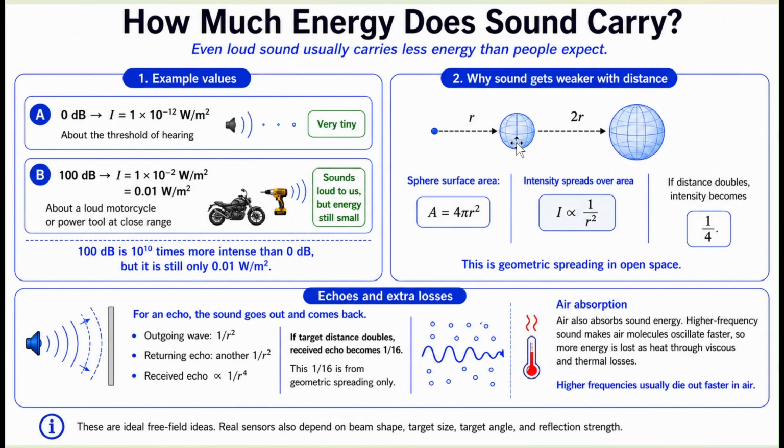So if in this small ball we had 1 unit of energy for every centimeter, now if we double the distance, we have a quarter, okay? This is very important for ultrasonic sensors because for ultrasonic sensors to work, again, we need that energy coming back, and I'll explain soon how that works, but the sound wave now is going there and back.